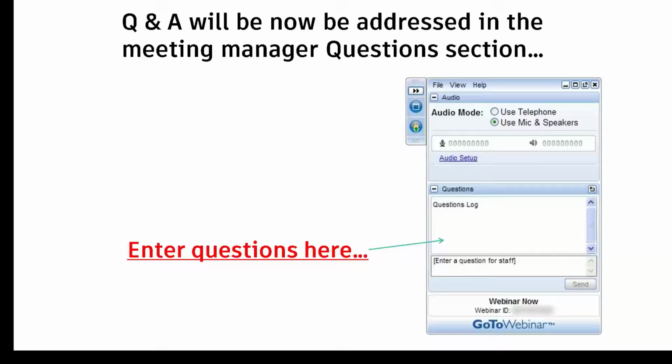You could be in a situation where, well, maybe you didn't fill out all of the Inventor properties, you left a couple of them blank. In those cases, many times NASTRAN will flag you and say, I can't assign this material because that particular field, like if you left Young's modulus blank, okay, that's not going to work. You're going to have to put something in there for that material. There are other material properties that it can actually calculate based on the situation. So it's a little bit give and take. But if NASTRAN needs something from you, it's going to tell you.